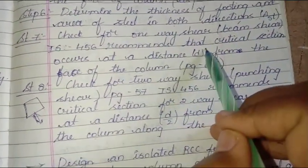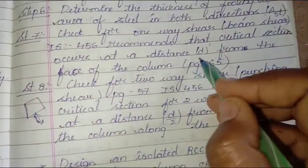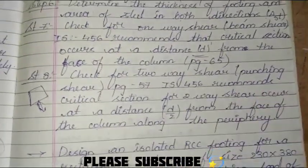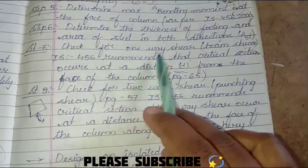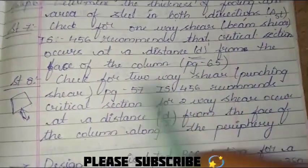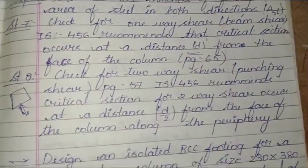Check for one-way shear, that is the beam shear, using the IS codal provisions. The critical section occurs at distance D from the column. Then check for the two-way shear. Very important, guys: whenever we are discussing the footing, we have to check for both one-way shear and two-way shear. Remember, one-way shear is called beam shear, and two-way shear is called punching shear. One-way shear, beam shear. Two-way shear, punching shear. It is very important, asked in many competitive exams already.